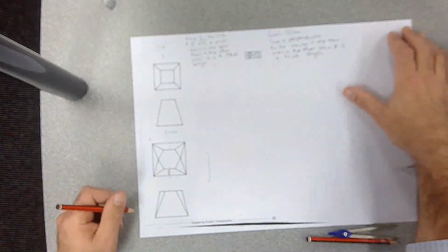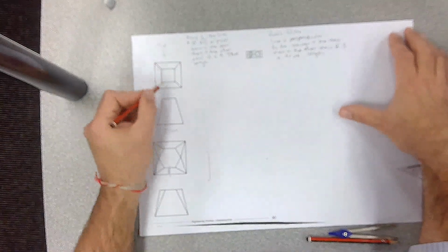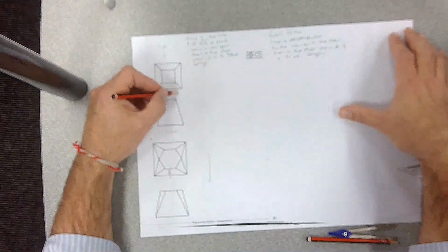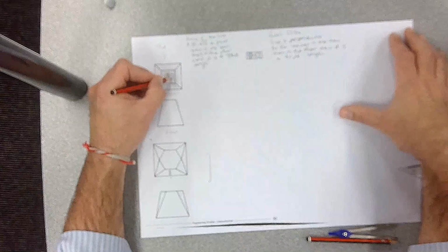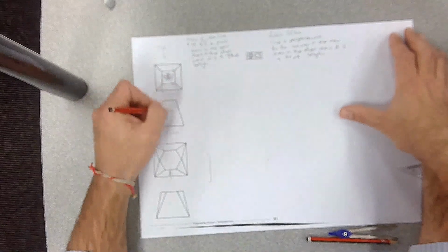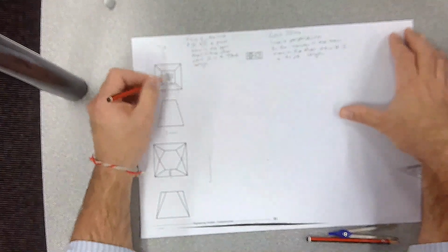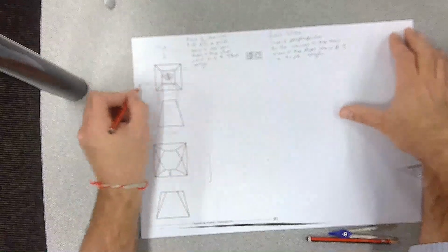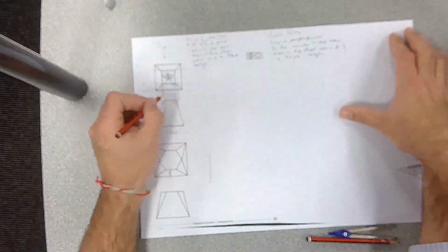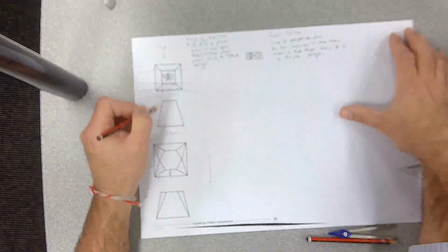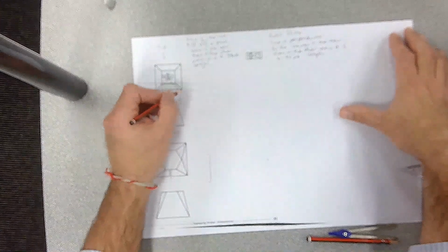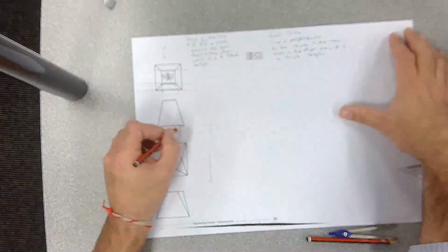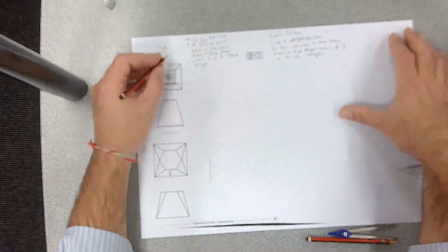So what does that mean? That basically means if the line is perpendicular, so what you're going to do is imagine that there's a person here, that's the back of their head, that's their big ear sticking out. If they're looking at this object, any lines that are horizontal to him, in the other view are going to be true lengths, so that's a true length because that line is horizontal. That's a true length because that line is horizontal, perpendicular to the viewer.